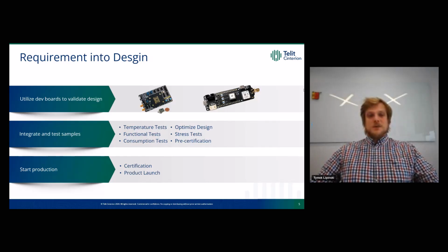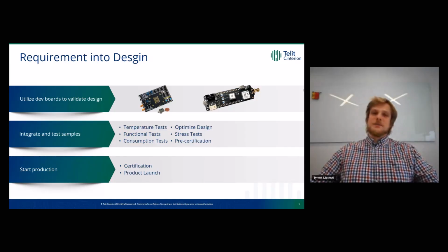When we are ready with our design and dev boards and so on, we integrate and provide test samples. And we do excruciating tests regarding temperature, functional, power consumption, design optimization, stress testing, and pre-certification. We want to score the pre-certification because when we launch the product, we just do start of production and we do one final costly but single-time certification, and we are ready to launch the product into the market.